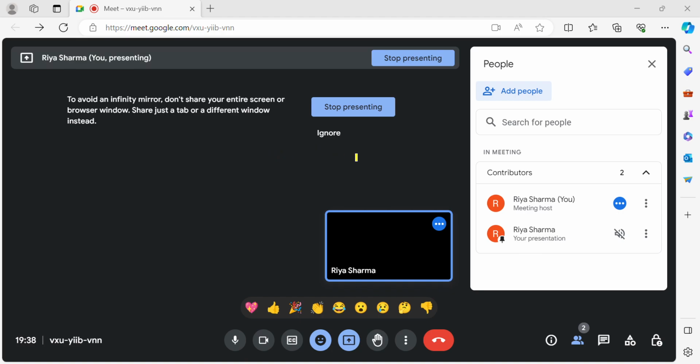Cp of air is 1.005 kilojoule per kg degree Celsius, and delta T of air is 85 degrees Celsius minus 25 degrees Celsius. This was the value given to us, and the exchanger is losing heat at a rate of 25 kilojoule per second. If the exit temperature of the hot air is 20 degrees, it was given that 15 degrees was the inlet of the water. So the outlet is what is wanted for the cold water.